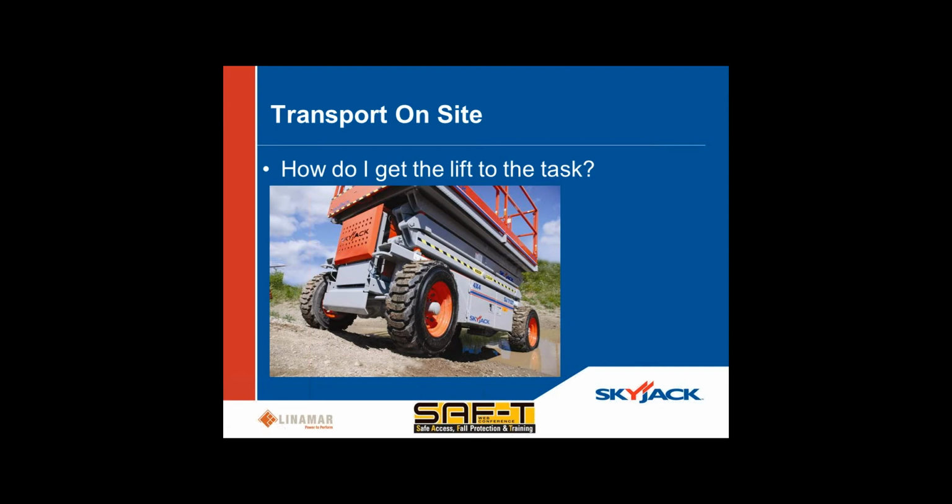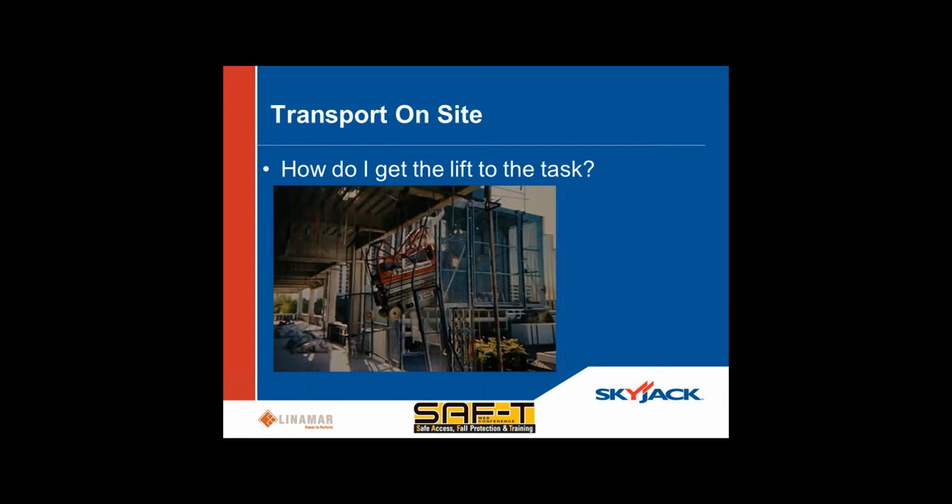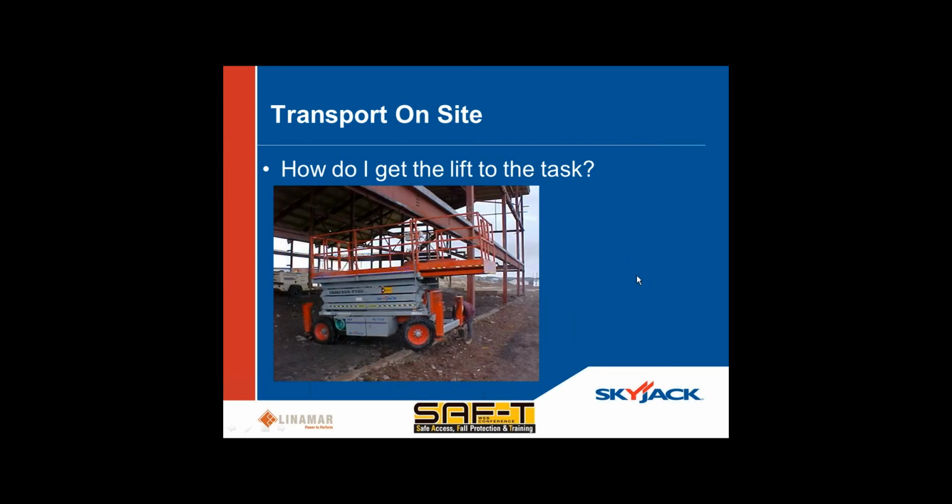task. And if immediately below your task looks like this and it's not suitable to elevate, you may need a machine that allows you to reach from a place that is suitable to elevate to where you need to work. That one's a little difficult to see as well, I apologize, but that is a scissor lift on an elevator that was not quite properly installed on it, or not quite properly tied down to the elevator, and eventually was crushed between the elevator and the structure.